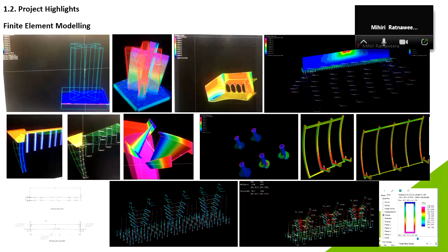My project director told me to start with a stick model, a plate model, and a solid model, and to achieve exactly the same result before proceeding any further. Then, once you achieve the result, use the stick model with varying parameters, justify all your results, and go ahead with your analysis. What that means is, in consultancy, time is always a critical element. You don't get months to sit there and enjoy your beautiful model and play with it. You get the stick model, you get the same result, and then you vary your parameters to try to get the best result for your client.